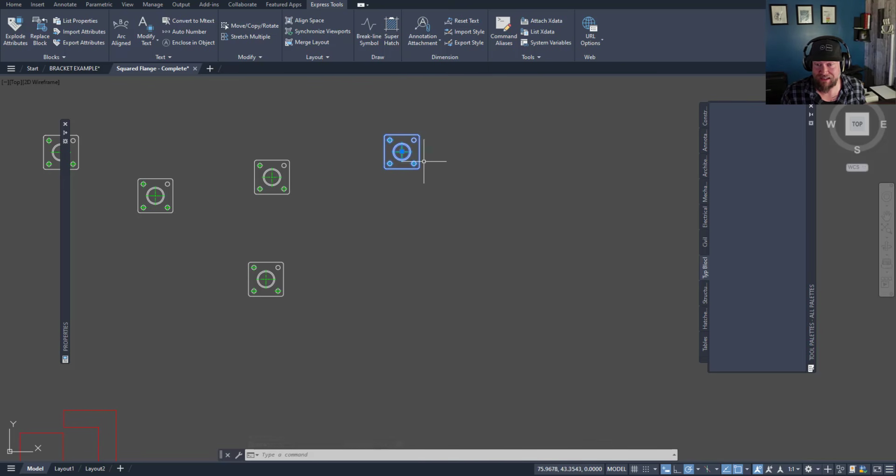I simply select it and then just click down on any of the line work, not the vertex. So just click and hold. You can see when I drag it over to my tool palette, it pops up to the top here. When I let go, it's going to place it into my tool palette. Now I've got quick access to this block by clicking and placing.